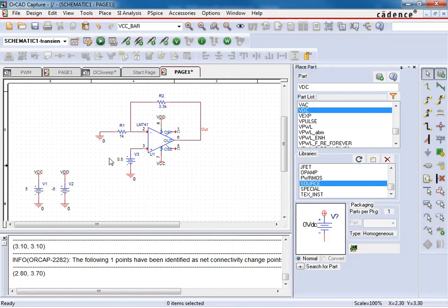Now we could do some other things here. For instance, I could label other nets here, and you can think of a net as a node. This net is essentially one node, and then here, this is all one net. It's the same net, and in fact if you hover over it, it tells you what the name of the net is. If you don't name them yourself, they give them some kind of unusual names. It's N00861. Well, that's still N00861 because it's just a wire.